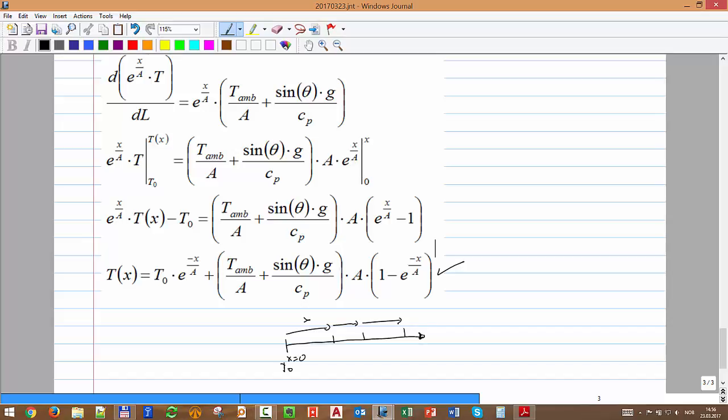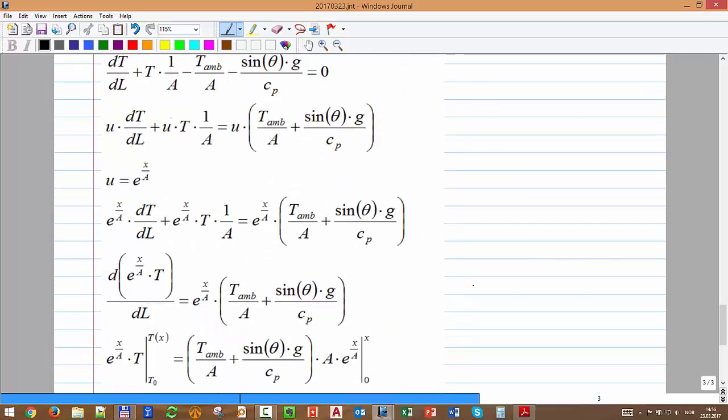Okay. Now some of you ask, what happens if, let's say, the inclination changes. Now I'm looking at different sections of pipe going up and down, up and down. So then I have to apply one equation for that segment, then I find the T inlet of the next segment, then I have to calculate U,